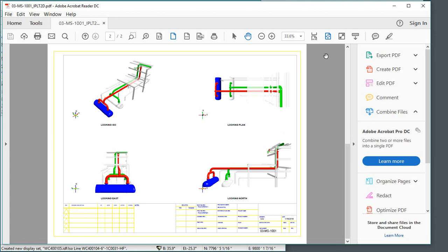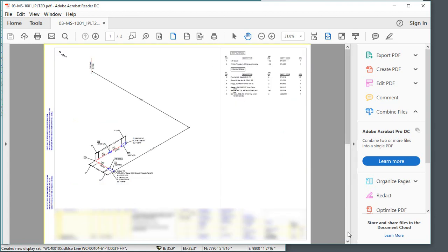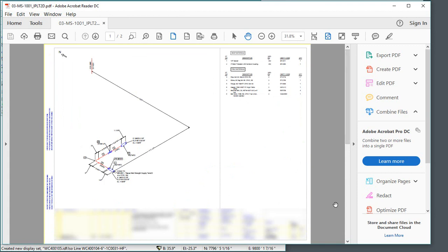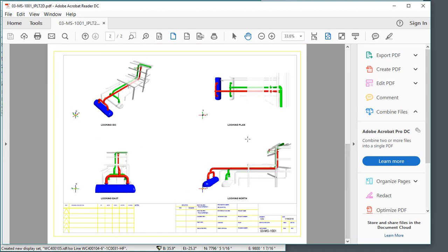So you can see for each one of your ISO drawings, you can create what we might call an enhanced isometric document that includes not only your ISO drawing but also the color-coded images to help anybody that needs to look at this ISO to understand how this line actually looks in the physical model. This might be a valuable document to your construction crews who have to go and erect this piping, to really give them a good sense of where they are in the model, where this line goes, and how it's configured relative to all the model objects around it.